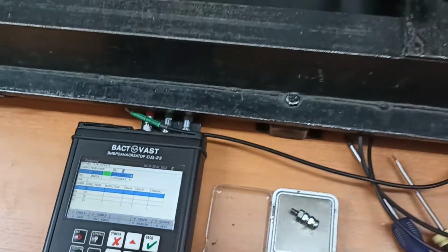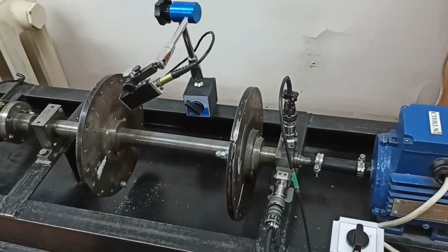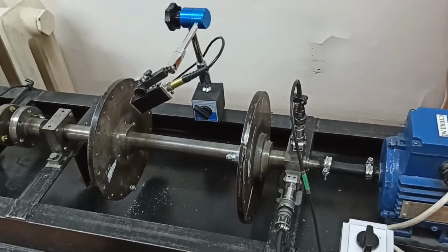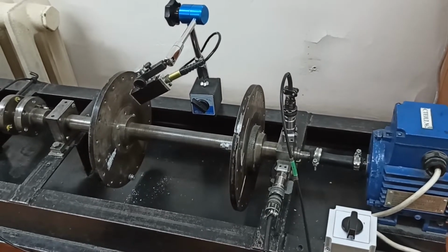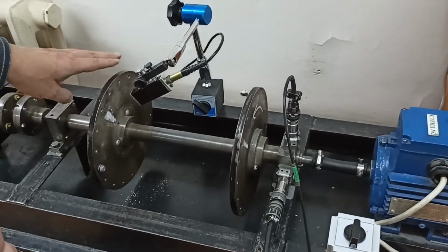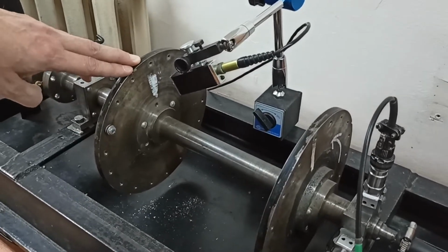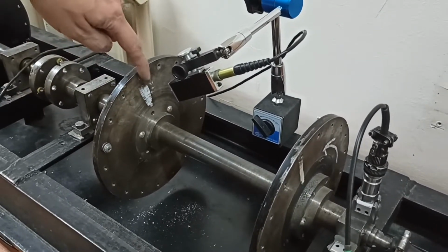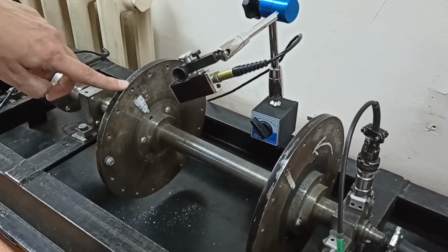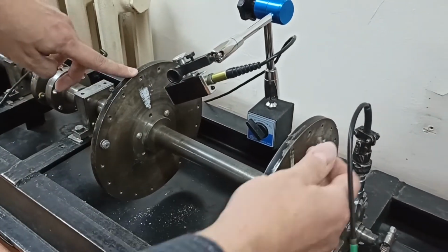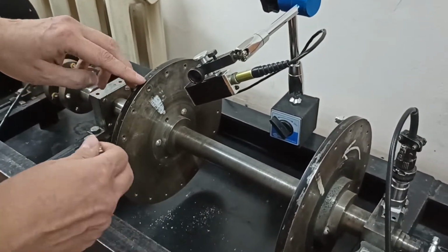Where do we install it? Generally, we can say that you can install it anywhere on the rotor. But we have done the initial measurement of run-in and coast-down, the actual coast-down, and it showed us the phase of 170 degrees. You can see it in the previous video. So 170 degrees should be measured from this mark, the reflective mark that we have on the rotor. So here. We take it with rotation, in the direction of this arrow, 170 degrees approximately.